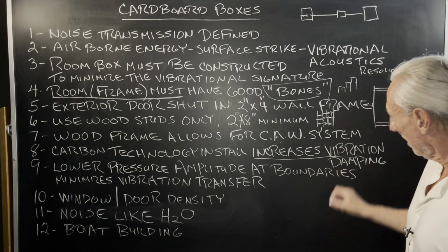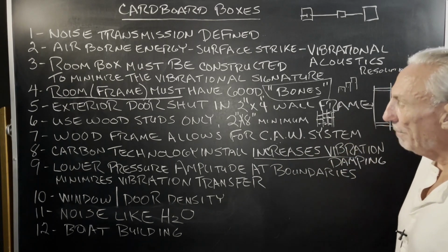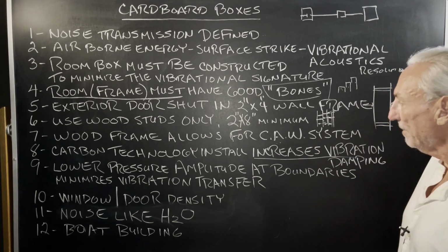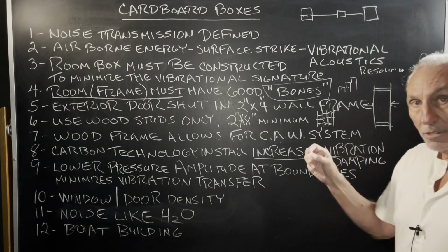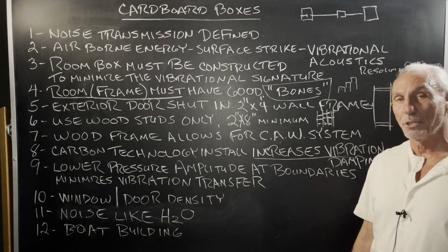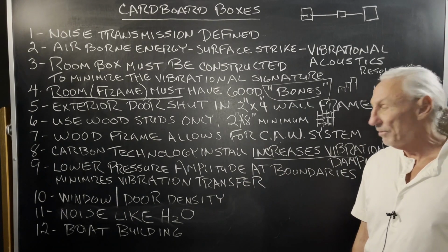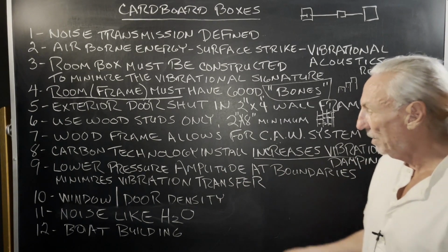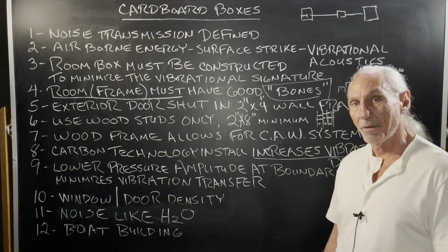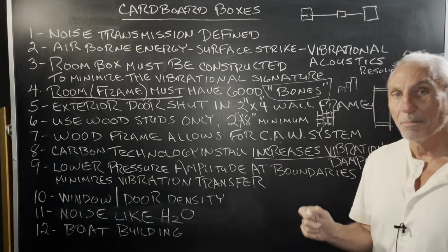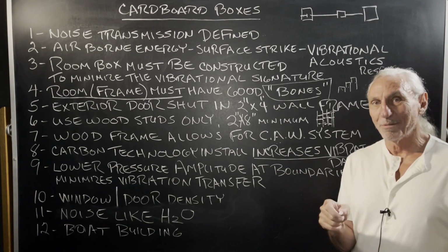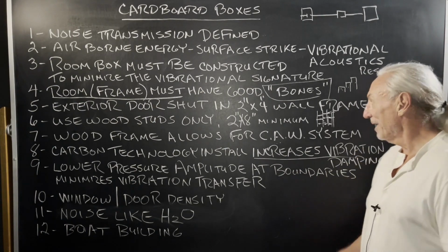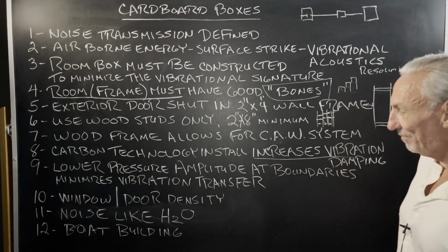Okay? So we're going to increase vibration management there with more rigidity. We're going to lower the pressure amplitude in the room. So that means there's less pressure pushing against the structure and the walls. And then we're going to minimize the transfer of vibration. Everything has to be designed to minimize the problems of the thing before it. Like I say, it's a step-by-step process.